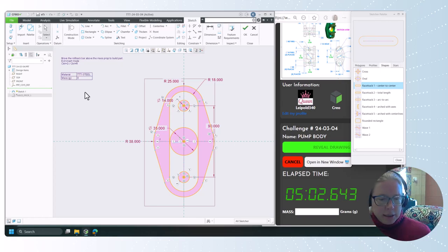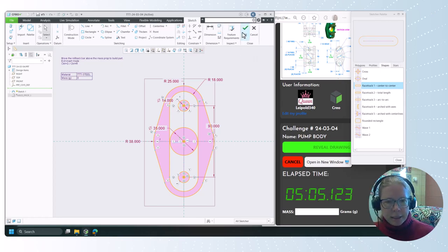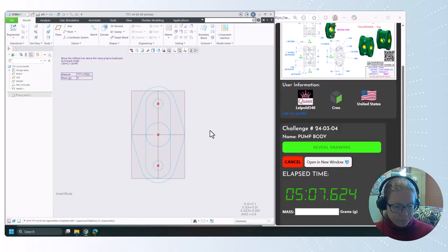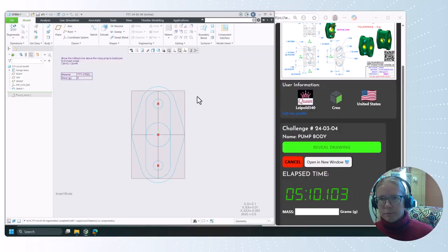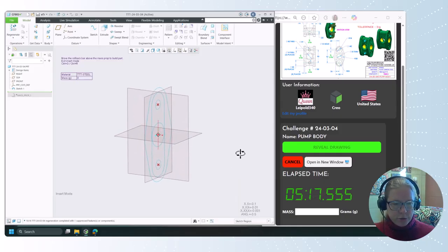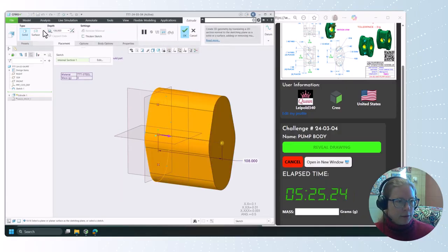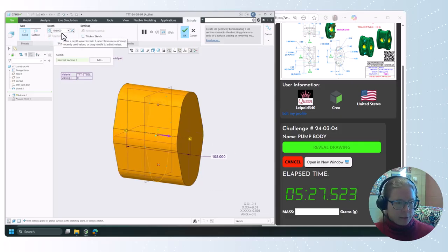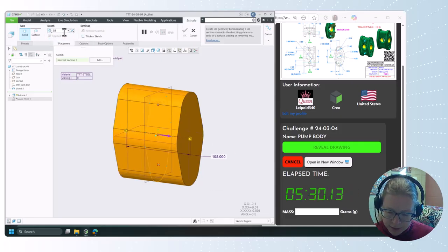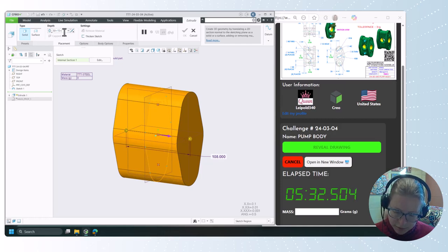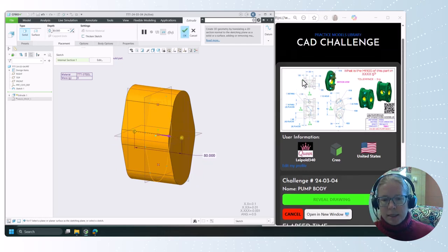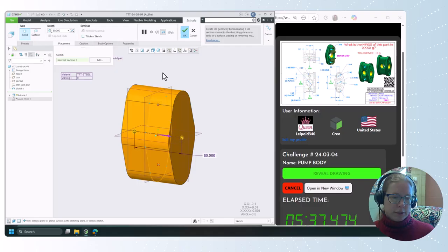Okay, so that's my full side view. And you know what? Let's go ahead and get that. Nope. Yep. Yeah. So we're going to use sketch regions. And we're going to start by extruding kind of everything. Let's get everything. We're going to extrude the whole thing symmetric with a 50 plus 15 plus 15. So that comes from the top view. We have an overall width of 80.